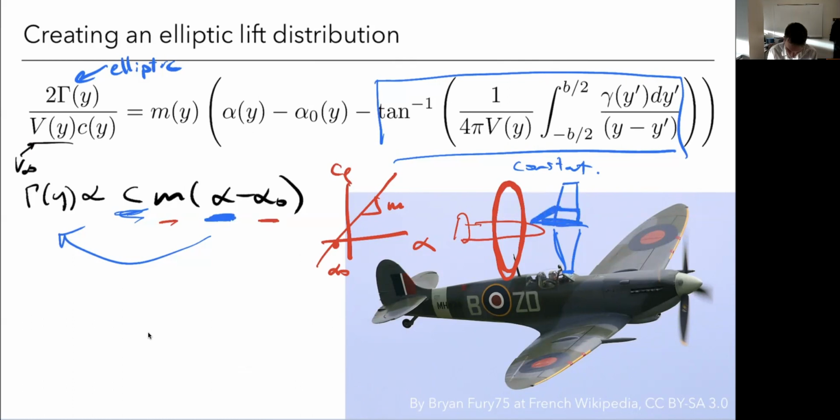So a linear block here and a linear block here. So I have more space here for landing gear, bigger chords at the root where I have more structural loading. And to increase lift where I lose something near the fuselage, but I don't create these complex curves generally because it's unnecessary, right? I can manufacture simple shapes that give me more or less what I want, and then add some twist to kind of fine tune the shape.